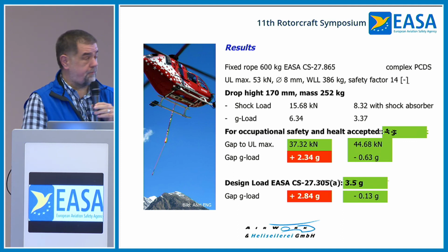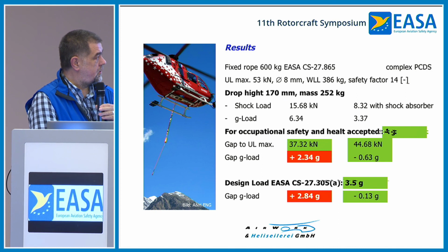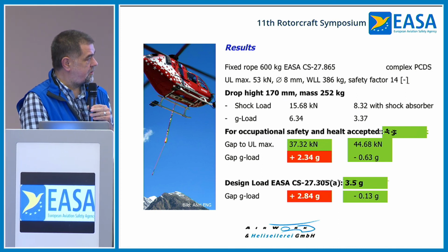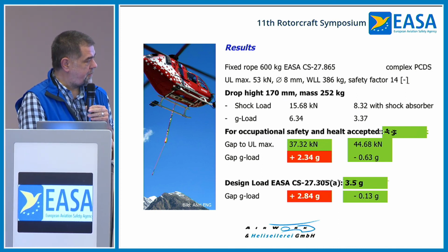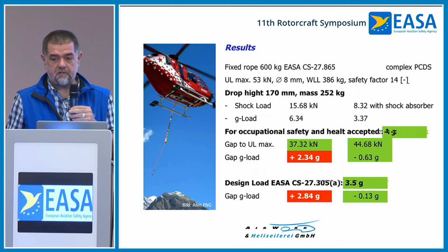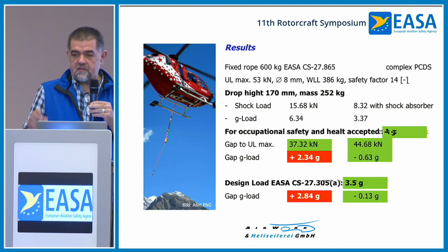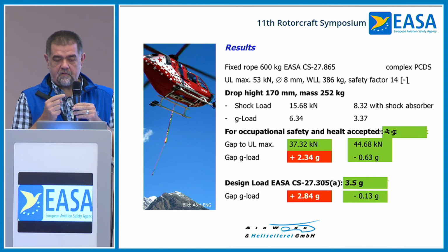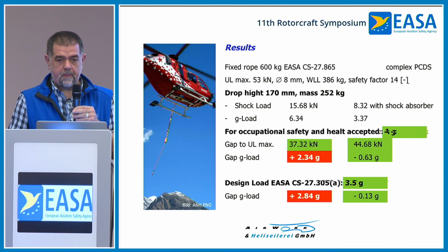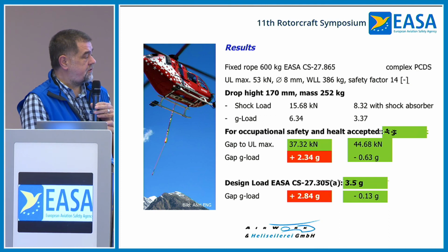We have a big gap here in the G load to the accepted G load, and a big gap to the accepted G load by the EASA rules. We tested also, in this case, without the damper, and the result with a damper.